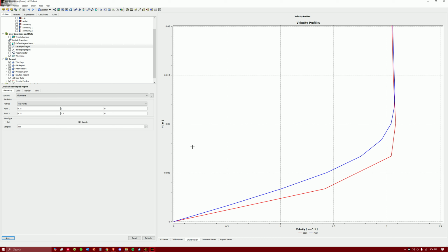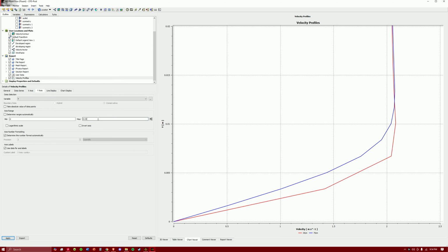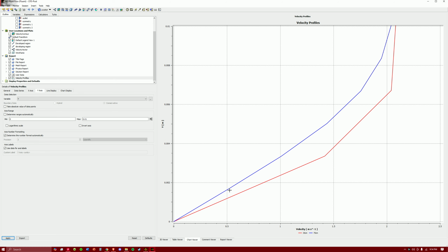That's because that boundary is getting thicker. So those are your two velocity profiles. You can compare it with Blasius's. It's going to look a lot like the blue one, especially if we go to our graph here and reduce our y-axis even more, down to, I think, 0.1 is when it looks really good. Yes, this is very similar to what Blasius's is going to look like, which is the expected. Blasius isn't perfect, but is a very good estimation of viscous laminar 2D flow.